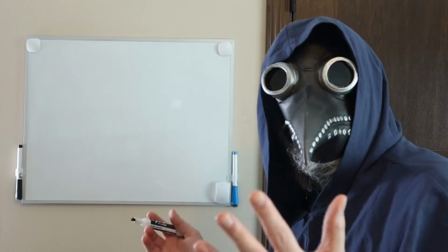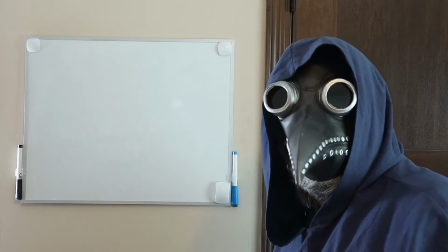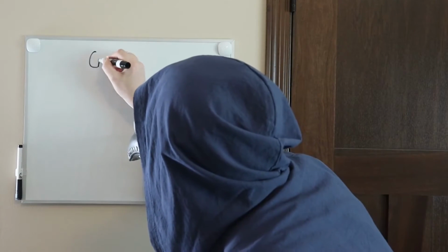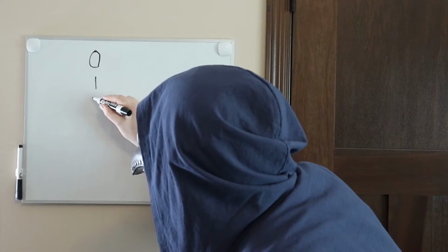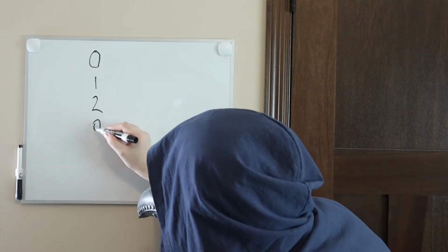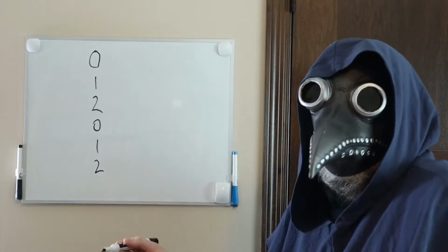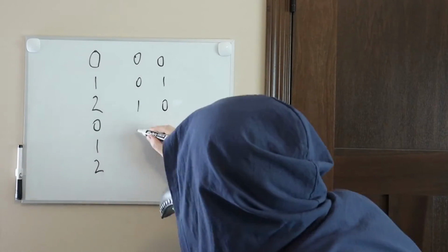Notice that what we are trying to do is to divide the frequency by 3. So if we use the input clock to start counting from 0 to 1, then 2, and repeat 0, 1, 2, then we're getting close. Let's write this sequence out in binary.